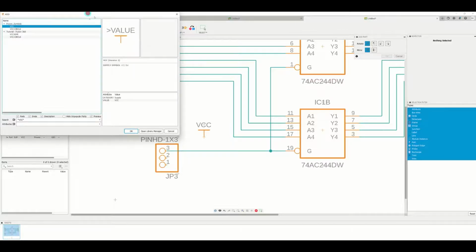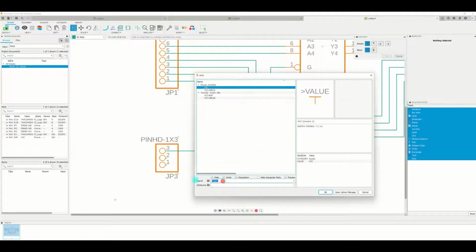So this time we now type ground to find ground. So asterisk GND, ground line. You can use that one or this one or this one. Most of the time we use this, no, in our symbol, but really this is a ground to earth, meaning the pins are connected to the casing of the board, but sometimes you don't connect the ground to a plane, so you can select this ground one for this one, and then you put a value of GND.